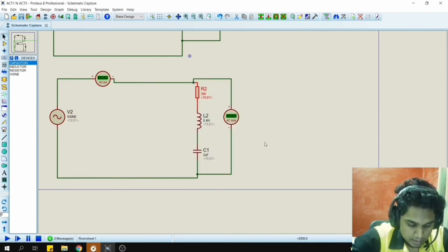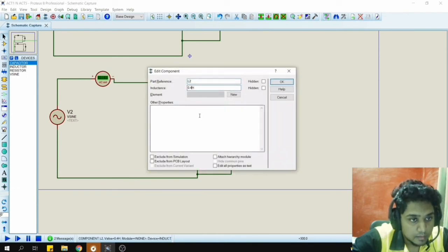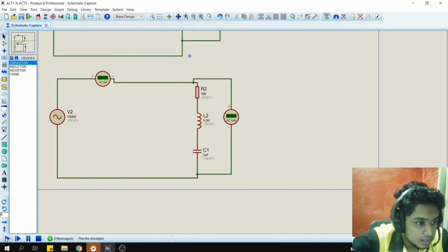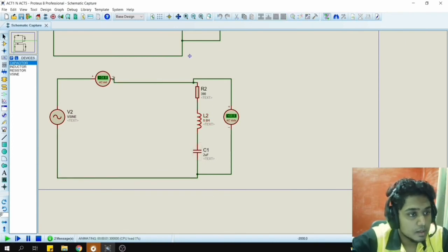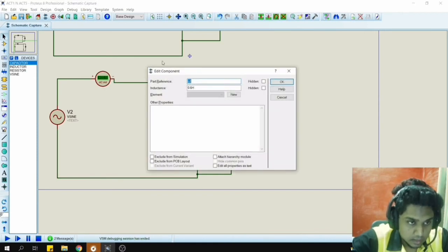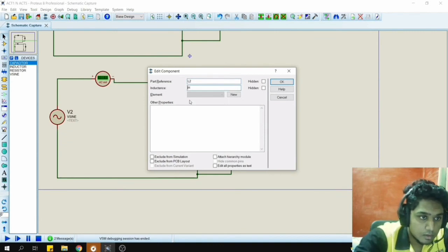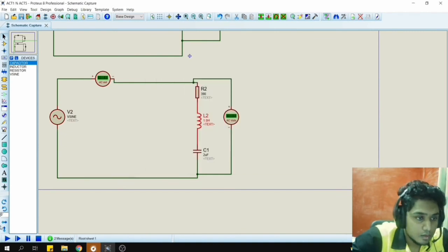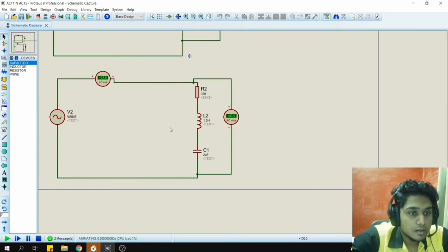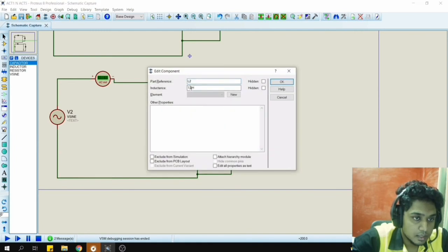And now let's increase the inductor to 0.6 Henry from 0.4, the rest all kept the same as the initial. We get 34.8 milliampere at 50 volts. Now let's increase the value even more to 1.0. From here you can see it's 38.0 milliampere at 50 volts. Now let's bring this back to 0.4.